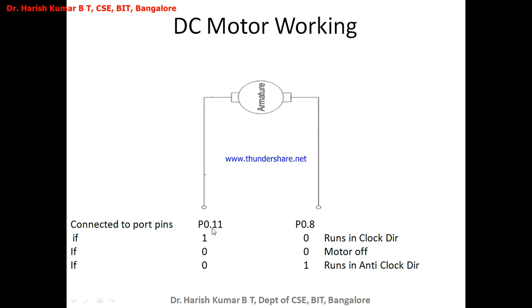This terminal is connected to port pin P0.11 of LPC2148, and this terminal is connected to port pin P0.8. If I apply say logic 1 to this particular port pin and 0 to this particular port pin, the DC motor starts running in the clockwise direction.